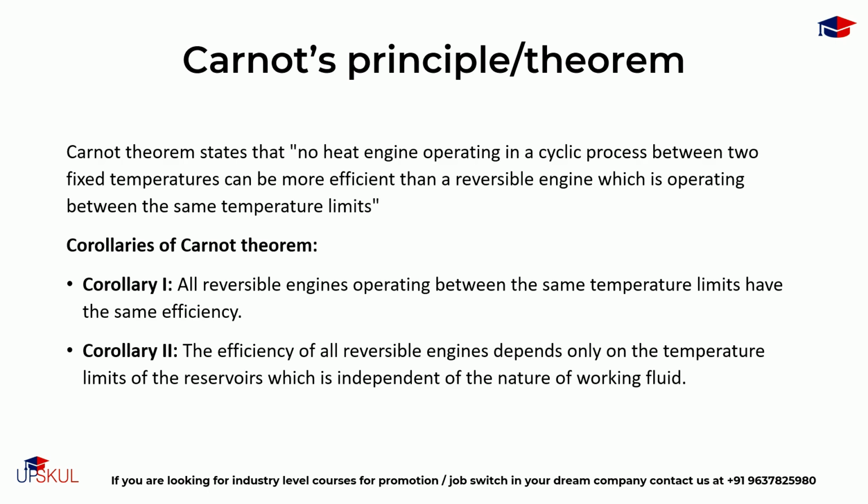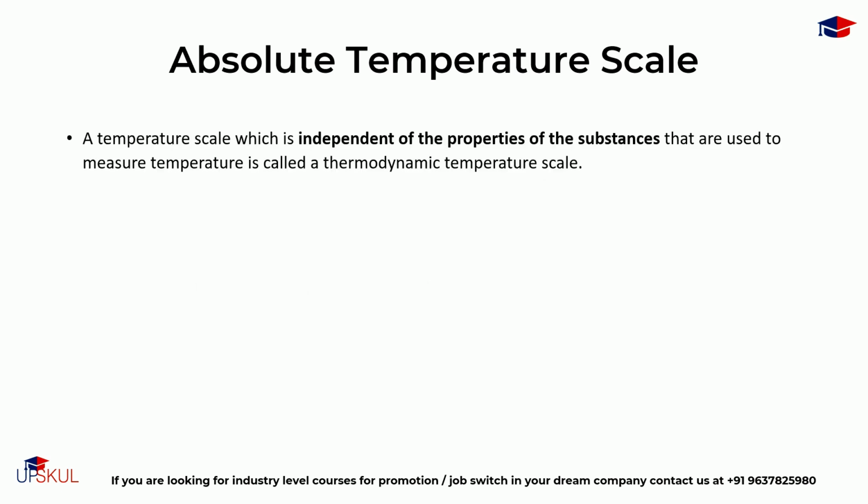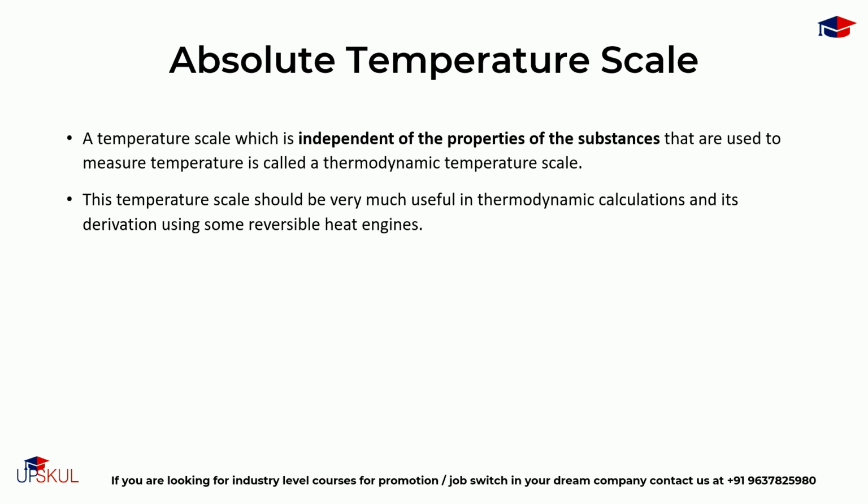Now, coming to the absolute thermodynamic temperature scale. It is a temperature scale which is independent of the properties of the substances that are used to measure temperature. This temperature scale should be very useful in thermodynamic calculations, and its derivation uses some reversible heat engines.